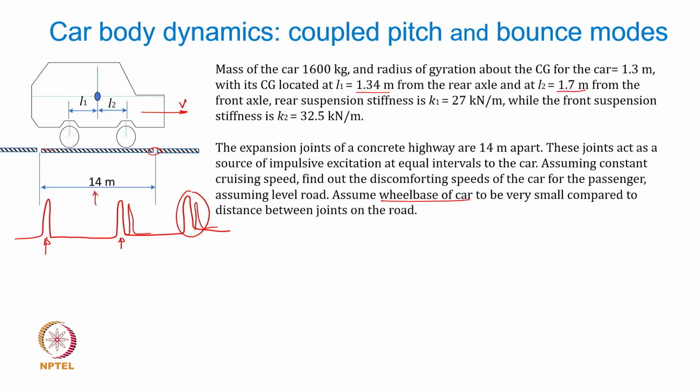We have found out that for a car body like this, there could be a pure bounce mode, there could be pure pitch mode, and when I say pure, it means the pitch mode and bounce mode are decoupled. If they are not decoupled, then you may have a coupled pitch and bounce mode, and then there will be two natural frequencies.